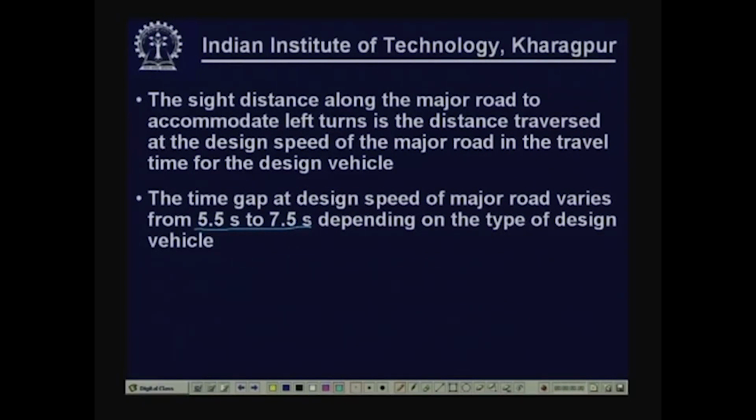And this value, 5.5 seconds to 7.5 seconds, varies depending on the type of design vehicle. So, for passenger cars it is 5.5 seconds, for heavier vehicles, commercial vehicles, if they are taken as design vehicles, then the required time is higher and it may go up to 7.5 seconds.